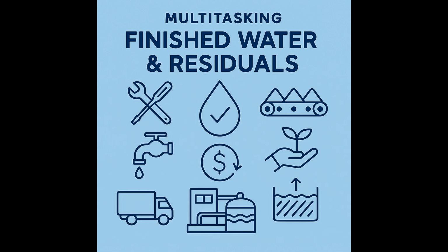Okay, so bench tests help dial in the chemistry. But what if a plant is thinking about buying a whole new dewatering machine, like switching from a BFP to a screw press? That's a huge investment. Absolutely. You wouldn't rely just on a jar test for that. That's where pilot testing becomes invaluable.